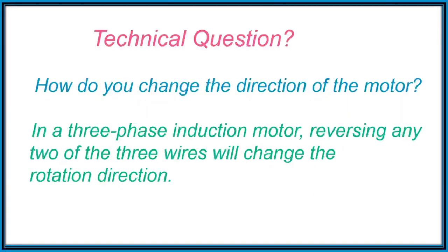Technical question. How do you change the direction of the motor? In a three-phase induction motor, reversing any two of the three wires will change the rotation direction.